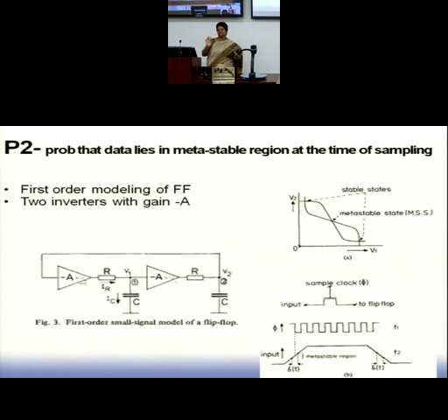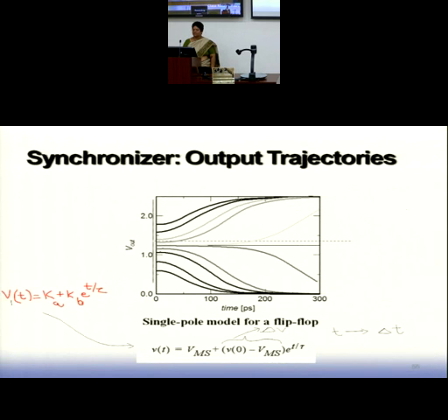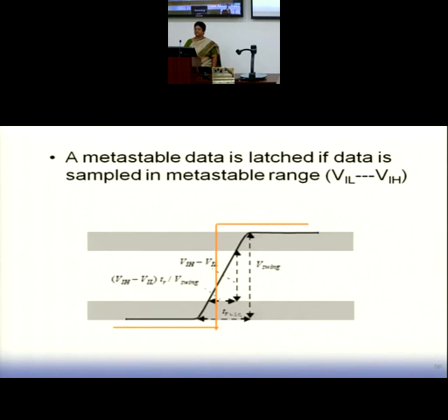Okay, he again does the same analysis, a bistable element analysis. This is what he says. He says that at a data clock edge, the data is not fully resolved. So when it is sampled, it is somewhere here. The red line is a clock edge. So when it is sampled at this edge, suppose it's an edge triggered system, your data is not fully resolved. It is within the range VIL to VIH. It is within this range.